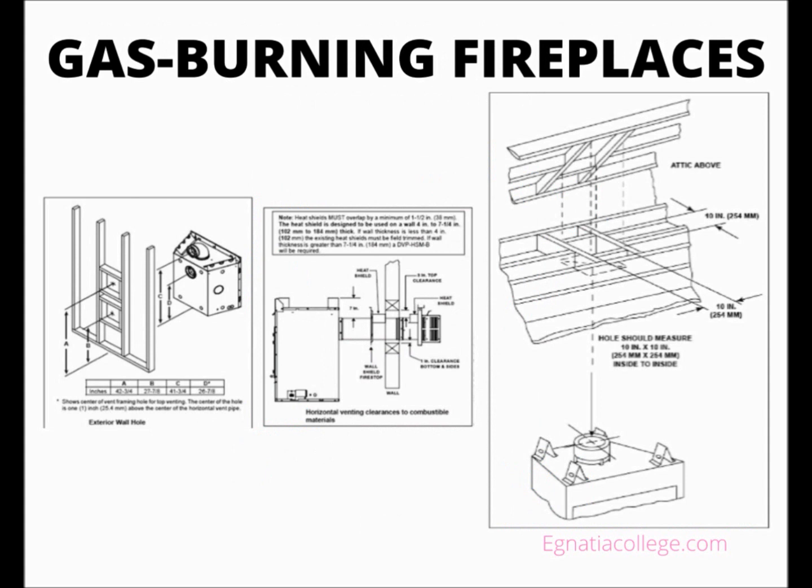Gas-burning fireplaces. Gas-burning fireplaces are a feature of many new homes and are becoming more common than their wood-burning ancestors. A gas fireplace is an appliance that is installed as a unit. The prefabricated unit is installed in a wood frame enclosure. Because the outer housing does not get as hot as that of a wood-burning fireplace, it can be installed closer to combustible wood framing. The unit is vented to the outside, and the gas line is connected to complete the installation. Any style of architectural trim can be applied to the front of the chase after the unit is installed.